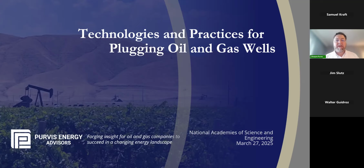But at the end of the day, in these conditions, there is one other thing to consider. The older wells certainly were earlier technology, but they've also endured a longer time period in the earth and therefore had more opportunity to break. And I don't know of any way to discriminate what higher leak rate is a function of technology during initial construction and what has to do with increased failure over longer time periods of standing idle. But if we do have a small leak, like a microannulus, it is theoretically possible for the cycling of water level or the movement of fluids or the very minute movement of the earth to exacerbate that issue over time and make it worse.